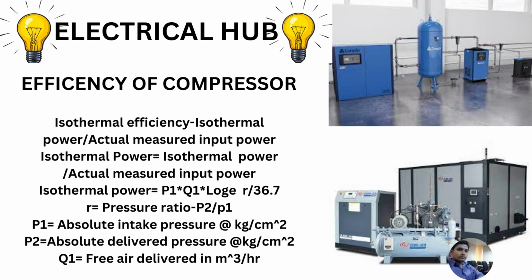Here R is nothing but the pressure ratio P2 by P1, where P1 is the absolute intake pressure in kg per centimeter square and P2 is the absolute delivered pressure. Q1 is equal to free air delivered.